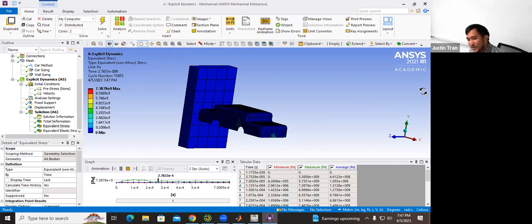These dynamic simulations are no joke. We did a ton of simplifications today. We use linear elements, linear elasticity, no nonlinearities, and it still takes forever to run a simulation, especially when you push it to those really high element counts. You set it, go cook yourself dinner, and then come back and hope that it's done.